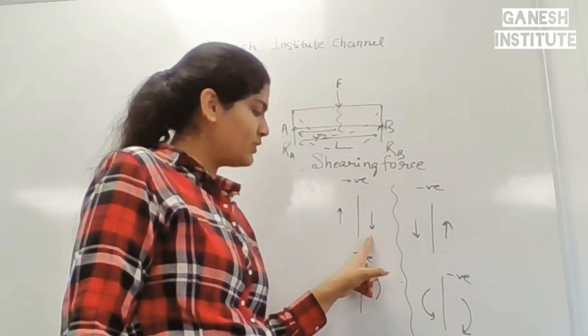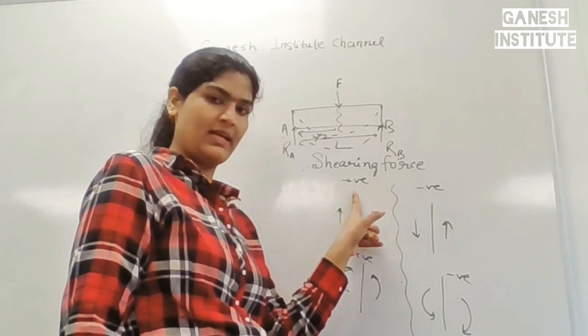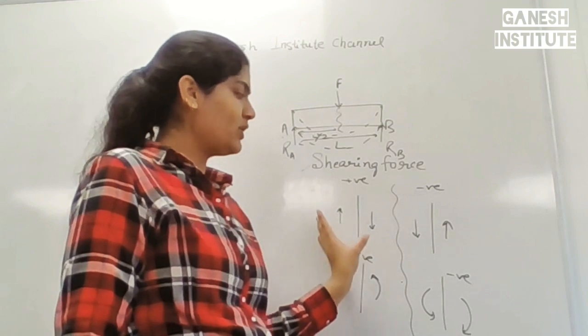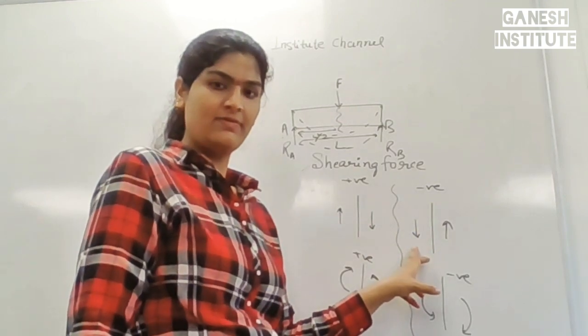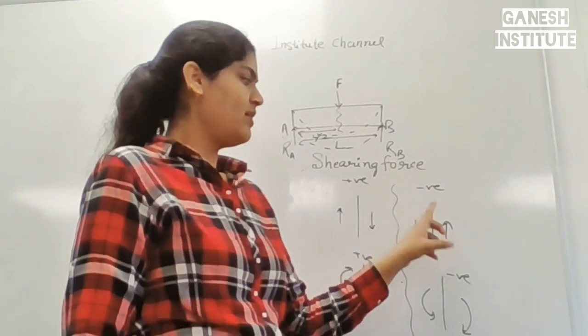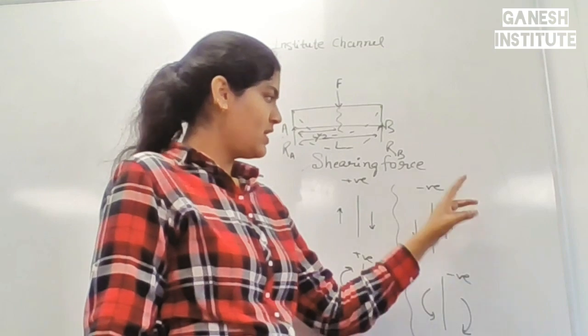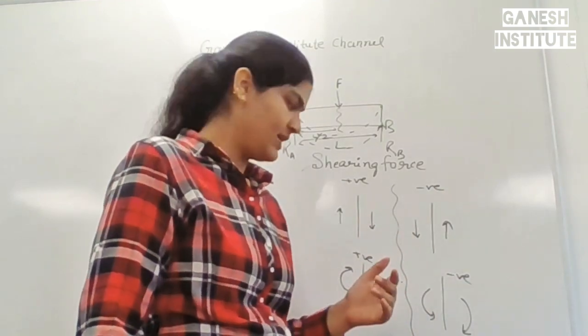If they are downwards but exerting on the right hand side, then we also take a positive sign. In contrast, when it is downwards to the left, we have to take negative. When it is upwards to the right side of the shearing surface, it is again negative.